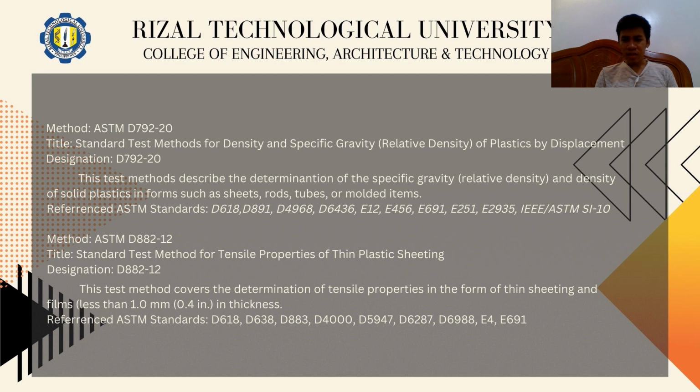Changes in density of a single material are due to localized differences in crystallinity, loss of plasticizer, absorption of solvent, or other causes. It is possible that portions of a sample differ in density because of their differences in crystallinity, thermal history, porosity, and composition.